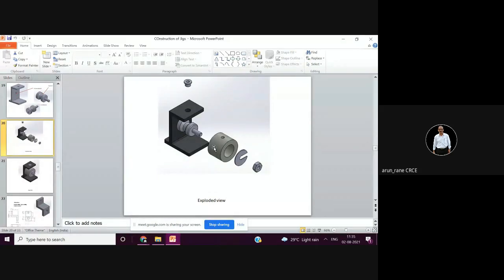You can locate two ends. So just finish the surface 10 mm here and 10 mm here. So that is sufficient. And the 80 mm in the middle, you can relieve, with an undercut like this. Okay.